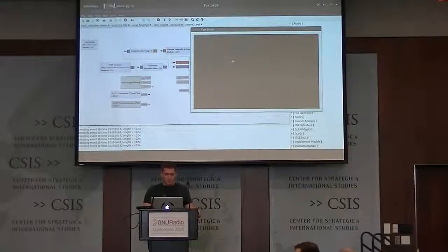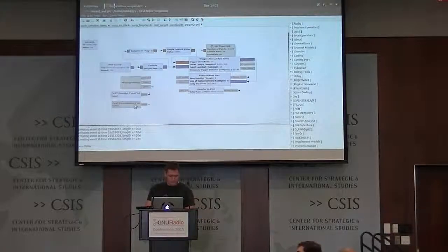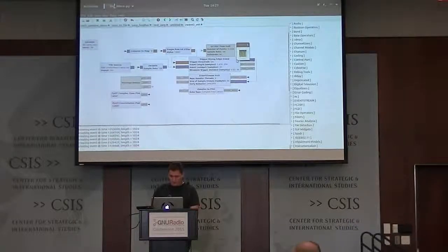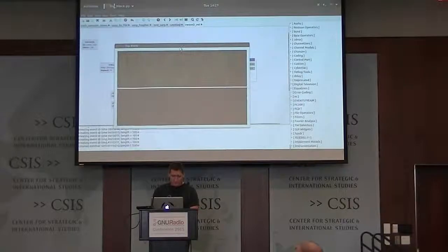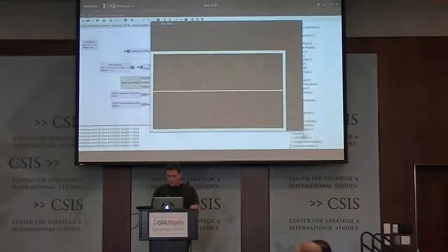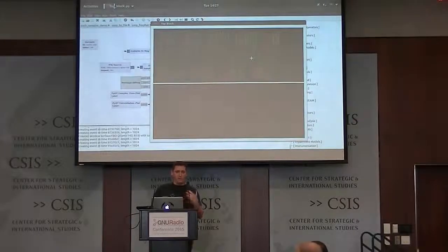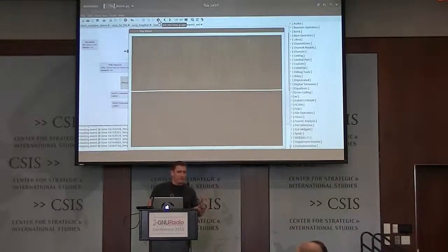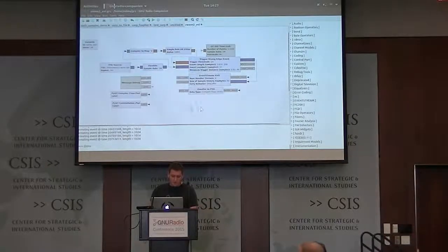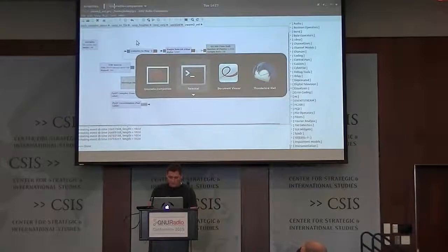You can zoom in on the preamble, or however you want to use it. Do the same for a constellation plot. It's kind of cool. Without any sync, right? Your next step would be to basically run this message worth of samples through some sort of synchronizer to start recovering whatever bits they're sending in the Z-Wave packet. All right. So that's a basic message-based plotting.